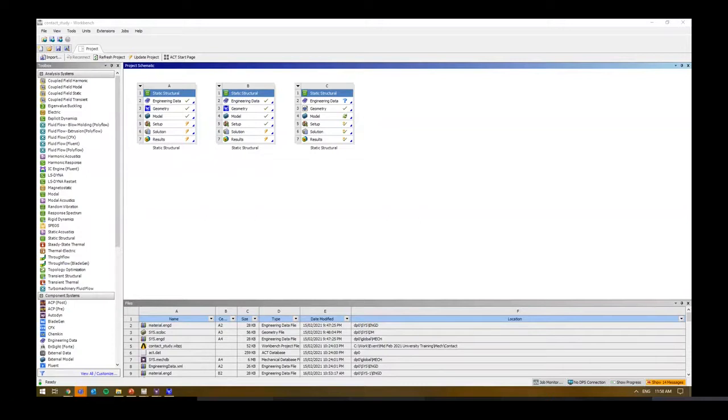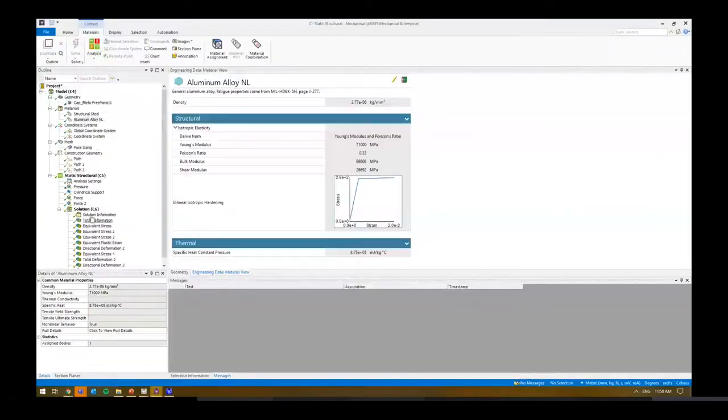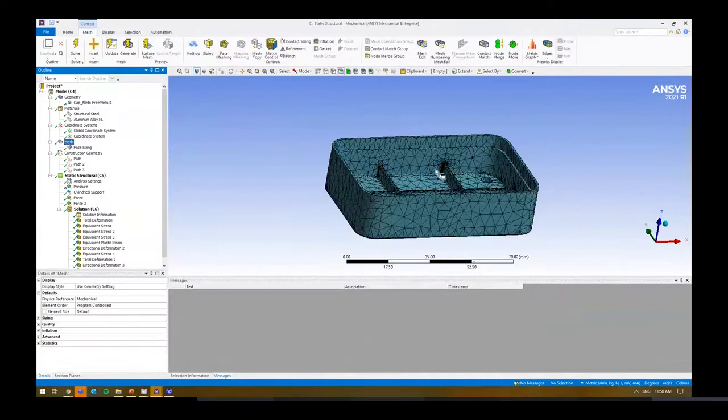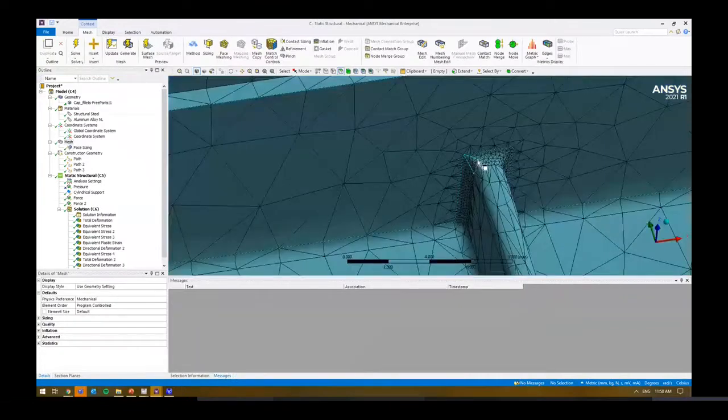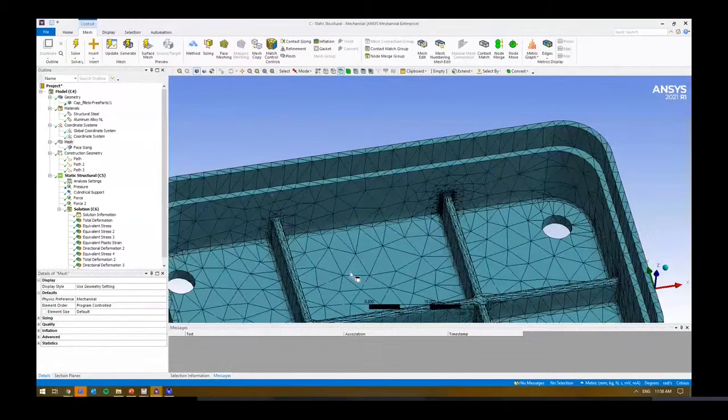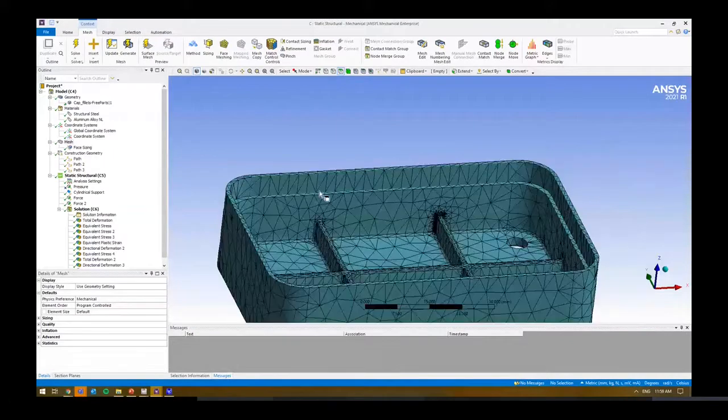And if beforehand you can identify where you might potentially have constraints and where you've got stress concentrations, that's when you probably want to go in preemptively and start to make some changes to the actual mesh, right? Refine around areas of interest. Make sure you've got things like curvature and proximity turned on if you need to capture some of these conditions as well.